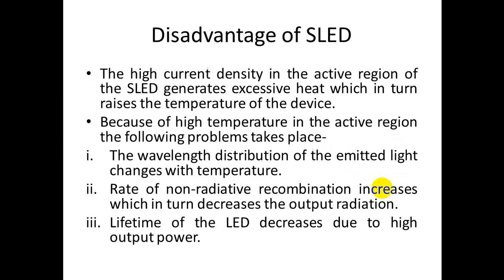So here are some disadvantages of SLED. Due to the high current density, the active region of the SLED generates excessive heat, which raises the temperature of the device. Due to this rise in temperature, some problems might occur. The wavelength distribution of the emitted light changes with temperature. The rate of non-radiative recombination increases, which in turn decreases the output radiation. And the lifetime of the LED decreases due to high output power.